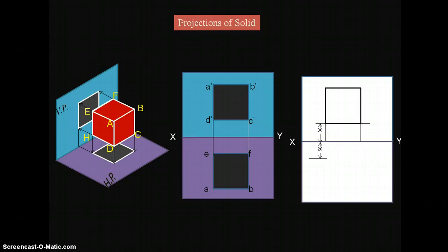From that projection line, again start the square. Before that I have completed the other projection line for the top view. In between these two projection lines we are going to get the square shape. Now start the square. Like this we'll get the top view. So these are the front view and top view. Like this we can draw the front view and top view.